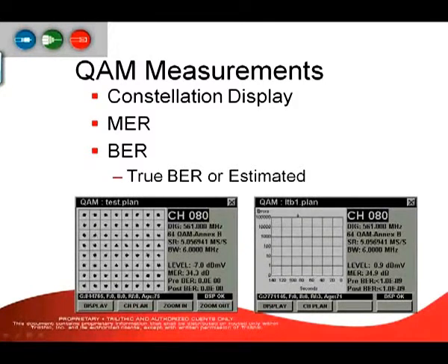I and Q streams can be represented as being in quadrature, forming a grid that offers I times Q possible states. The grid is conventionally referred to as a constellation and may be thought of as kind of like an array of boxes, with each box representing a particular I or Q symbol state. The ideal or nominal location for a given symbol state is the center of the box. That's that tight cluster of dots that we've been talking about. The boundary between neighboring boxes, like what was mentioned, is the decision threshold.